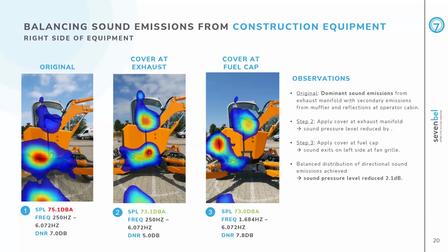The danger is always when you choose an acoustic camera which is too small, that you cannot resolve and find all of the sources, and you just get a compound blurred acoustic image which does not give you a lot of insight in terms of what your dominant sound emission really is. So especially when you're dealing with products having mostly low frequency sound emissions, mostly happening below 4 kilohertz, 3 to 4 kilohertz, you should always go for the largest available measurement surface in order to get results that point you in the right direction and make your analysis more comfortable and more to the point.